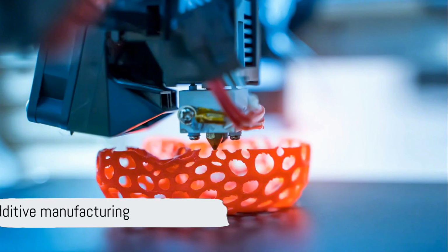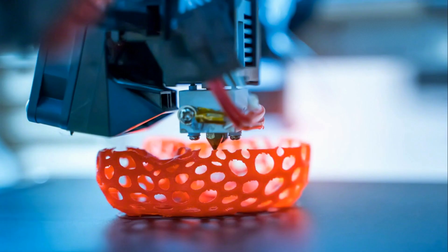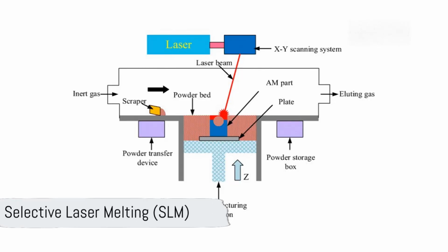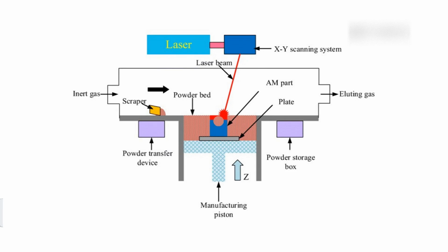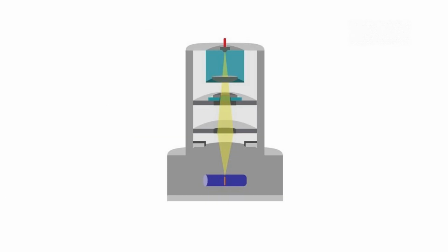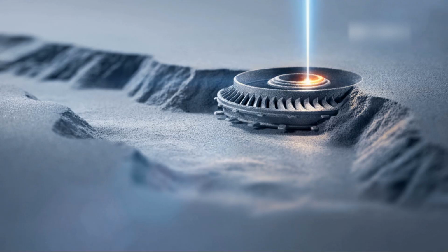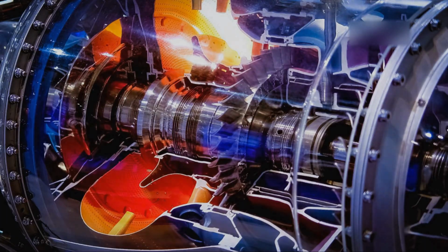Additive manufacturing plays a key role, especially for components with internal lattice structures or intricate geometries that traditional methods can't produce. Technologies like selective laser melting, SLM, and electron beam melting, EBM, allow engineers to fabricate parts layer by layer, using high-strength alloys like Ti6Al4V or 7075-T6 aluminum. These materials offer excellent strength-to-weight ratios but require careful post-processing, heat treatment, surface finishing, and non-destructive testing to ensure durability.